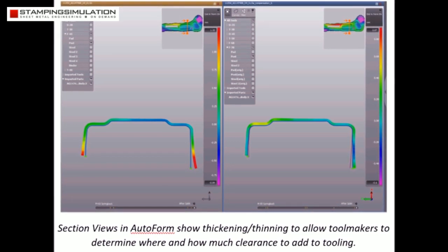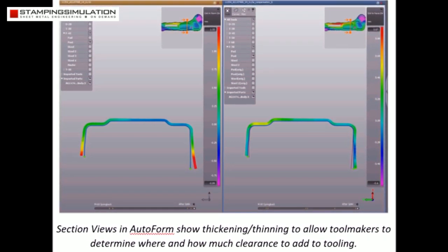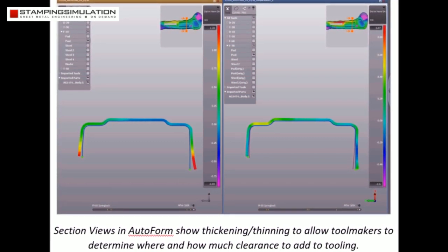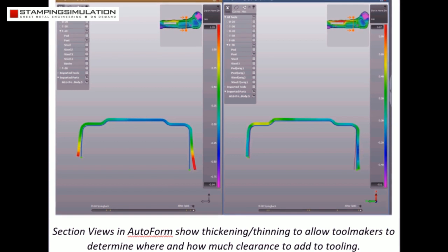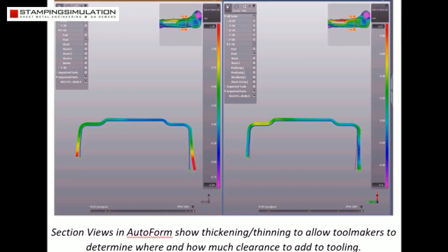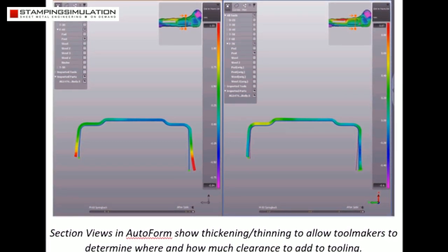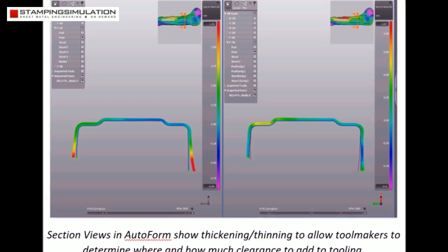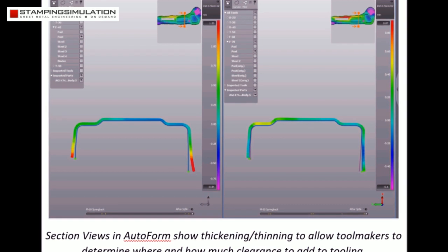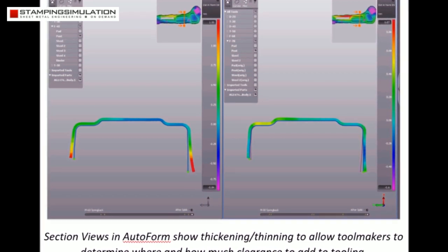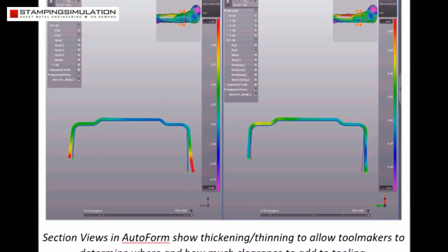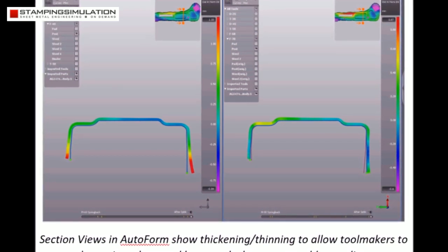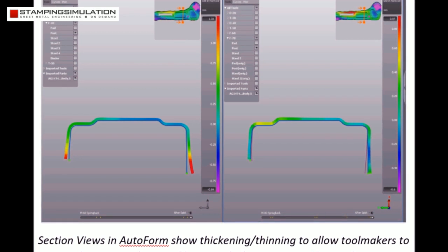4. Tooling clearances. Deep draws with vertical walls, for example cups, require special attention to clearances. Whilst many simple tools can be machined size for size with little or no clearance, deep draws, especially with vertical walls, cannot. Simulation uses perfect tooling and will show exactly where thickening will occur. However, tooling clearances must be added by the toolmaker to correctly allow material to flow, that is, avoid locking up during a complex deep draw or similar parts.